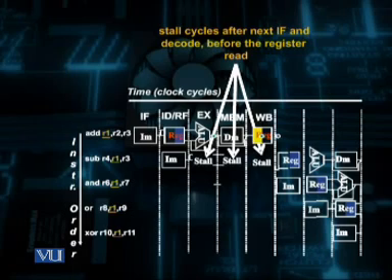Then the subtract instruction will get the correct data from the register R1 on the completion of the execution of the first add instruction. However, you can see that the introduction of these 3 stall operations very badly affects the performance of the pipeline structure.